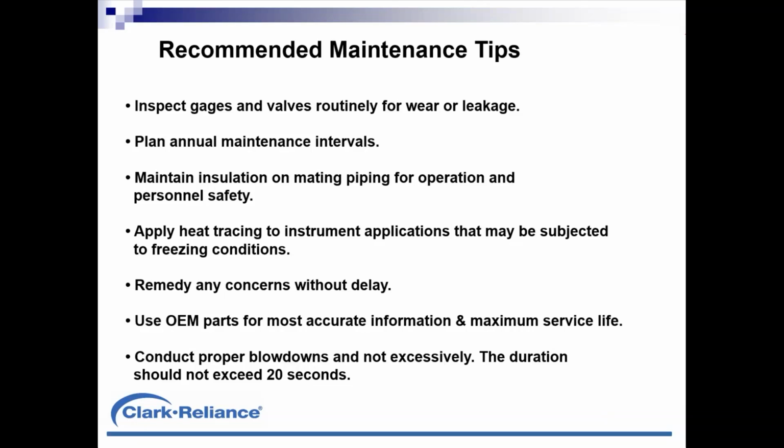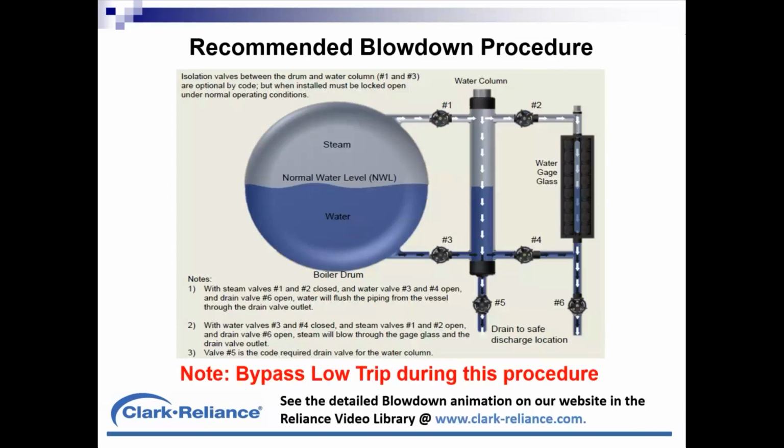Use OEM parts, OEM resources for the most accurate information for your instrument and also to maximize the service life. Proper blowdowns should not exceed 20 seconds. And here's an illustration that we contributed, and this is actually in section 7. And this talks about how to properly blow down instruments.